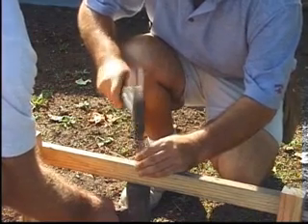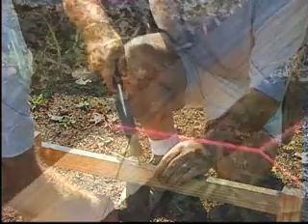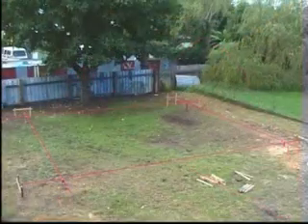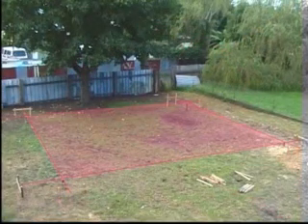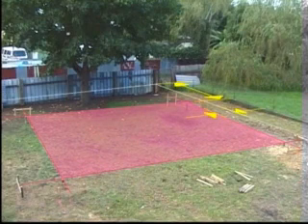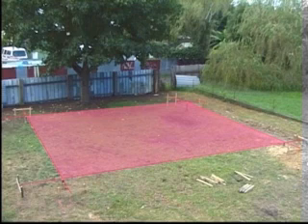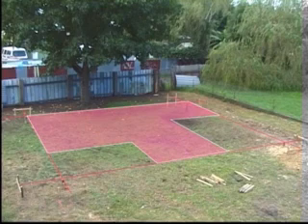Because all ledges have been levelled to the same height, the 4 string lines accurately set out the perimeter dimensions of the building correctly located on the site with the required setbacks. Not all buildings, however, are rectangular in shape. In setting out L-shaped or T-shaped buildings, the first step is to peg out the overall rectangular envelope that contains the building. Part or parts of this rectangle are removed to form the L or T.